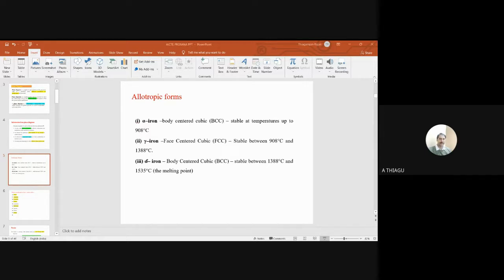50% of austenite is changed to alpha. You can see the small nucleation development of ferrite. Can you see this thing? So small ferrite has developed and the remaining 50% is austenite. So 50% conversion has happened at a particular temperature. Second, again the samples are allowed to cool.